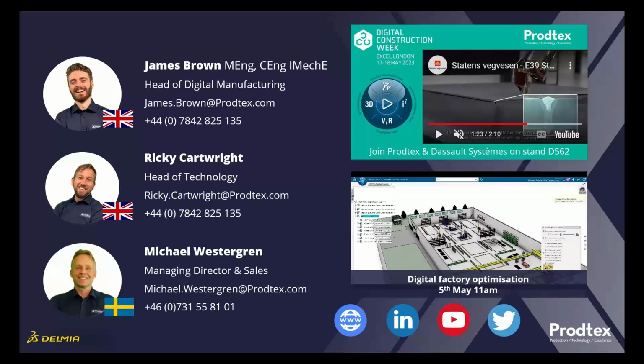It's a tricky one with the point clouds. Obviously, there are things you can do if your laptop isn't as good. You can split the point cloud up into smaller sections, or you can create extracts from certain elements of the point cloud to lower the impact when you're doing your day-to-day simulation work, so you don't have the full point cloud on there. We're probably not going to get into the exact specs of what laptop or PC would be great now, but we can certainly talk to you about that offline and discuss what would meet your requirements if there's something specific you want to go through.